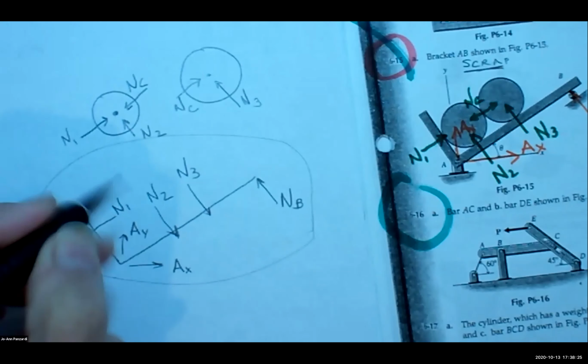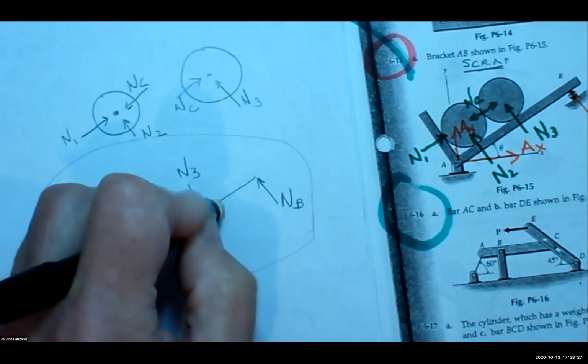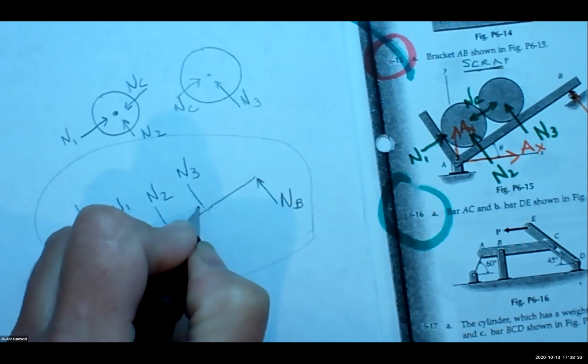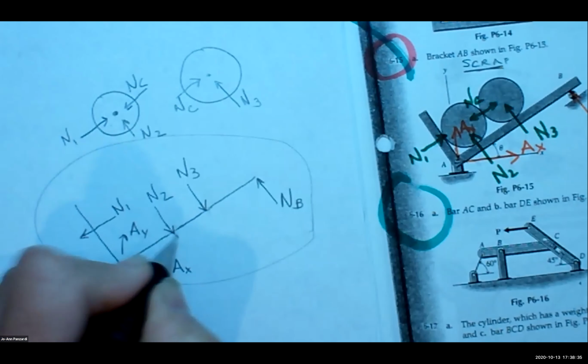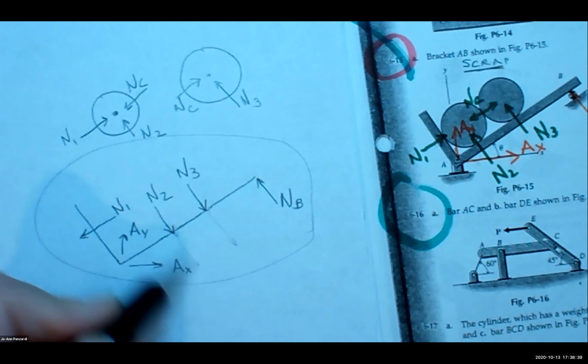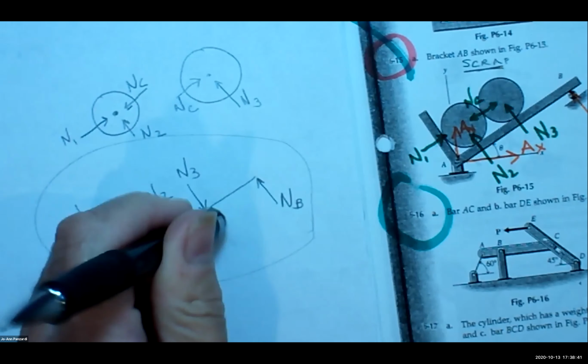Yeah, is proper convention for drawing these normal forces to draw them as a compression, or you're kind of drawing them through the bar, or does that not really matter? It doesn't matter, because some of you, you know, I probably, if I was neater, I would have drawn it like this, right? But some of you like to draw them out here. It doesn't matter. The point is that it's along that part.